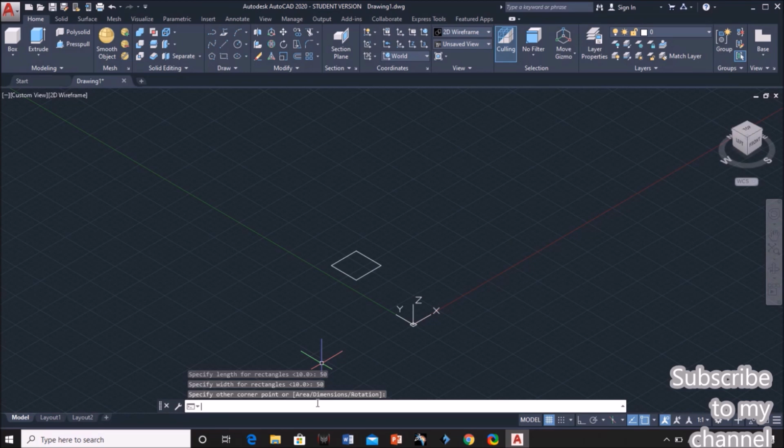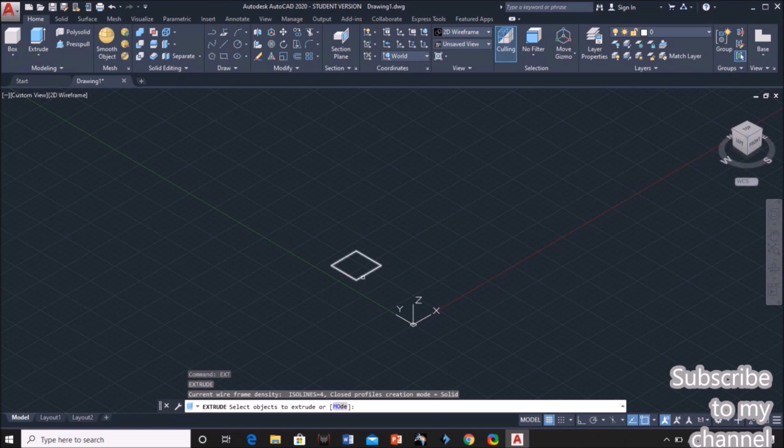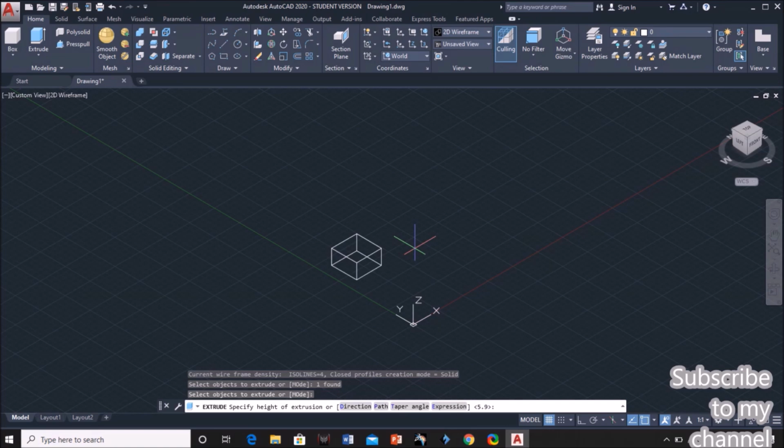Next, using the extrude option, EXT enter, convert this 2D object into 3D. It is asking to select objects to extrude. So select the object to extrude and click on enter. Next, specify the height. Now I am giving the height as, suppose, 60, enter. So the 2D sketch is converted into 3D, but it is still in the 2D workspace view.